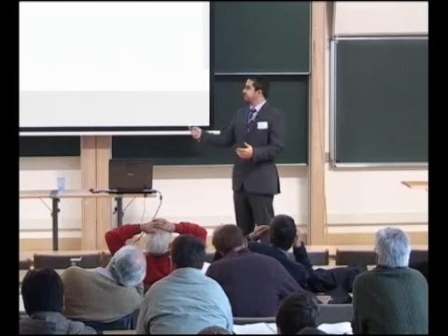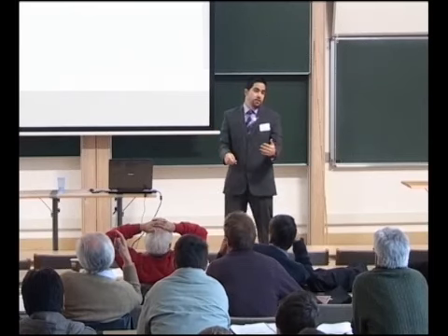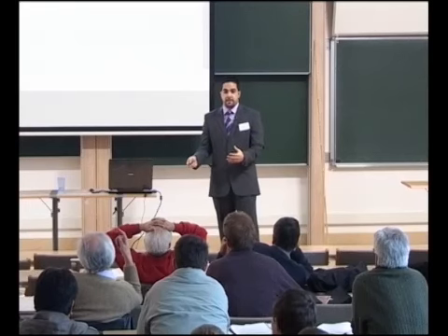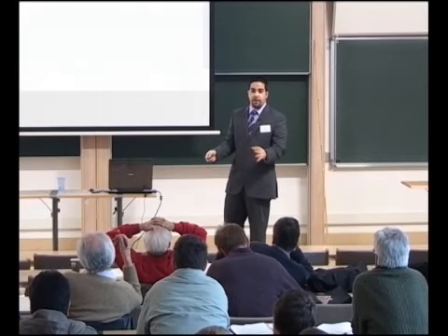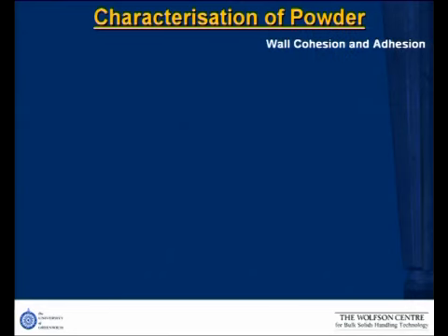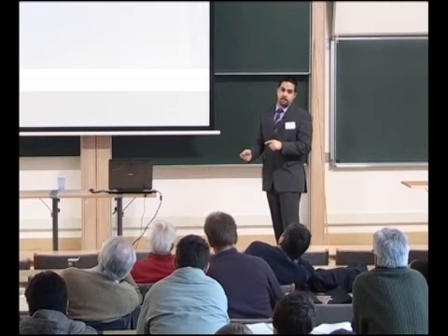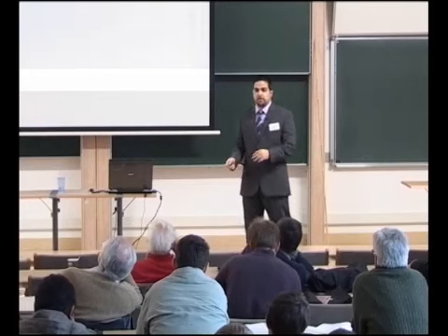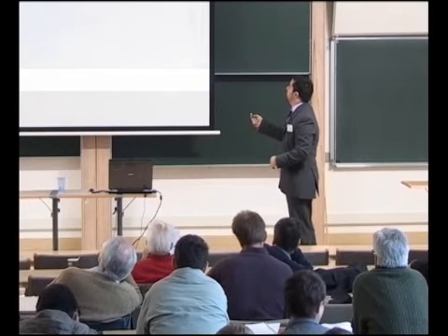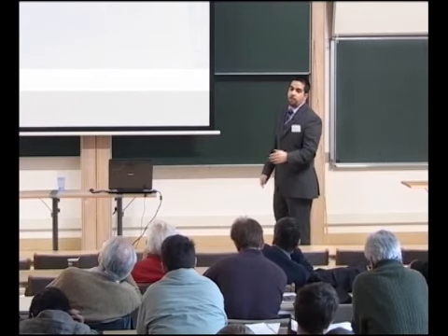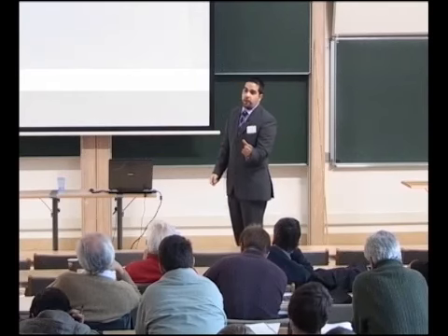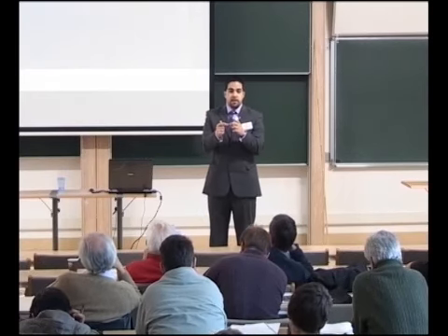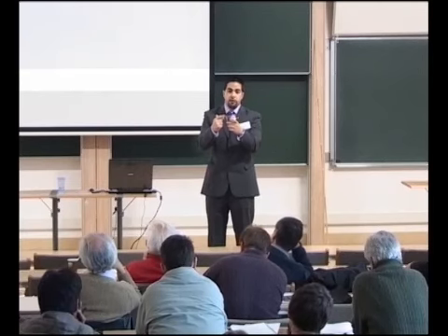Here are some calculations for the dosator and then for the bed. I'm not going to go into detail, but this model is not going to work if we don't do any characterization of the powder, so we may get wrong values. So let's talk about characterization of powder. I'm not going to talk about angle of repose or something like that, just some of the main ones. I'm not going to talk about fluidization because I don't have time, but let's talk about wall cohesion and adhesion.